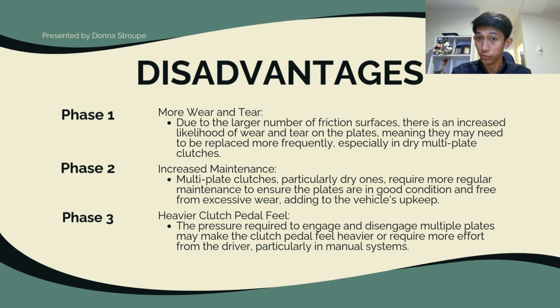And next up, we have increased maintenance, and this is because, particularly the dry ones, require more regular maintenance to ensure the plates are in good condition and free from excessive wear, adding to the vehicle's upkeep. And last but not least is a heavier clutch pedal feel, and this is because the pressure required to engage and disengage the multiple plates makes the clutch pedal feel a lot heavier or require more effort from the driver, particularly in a manual system.